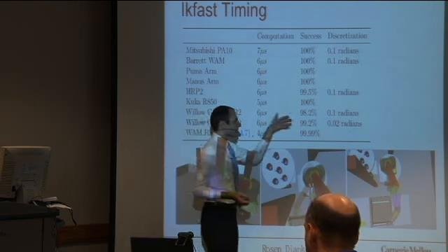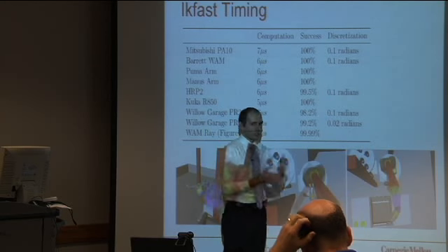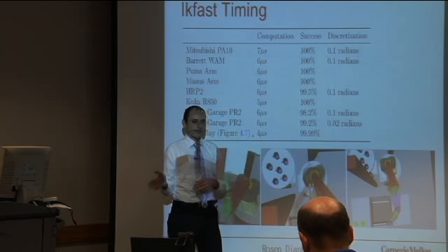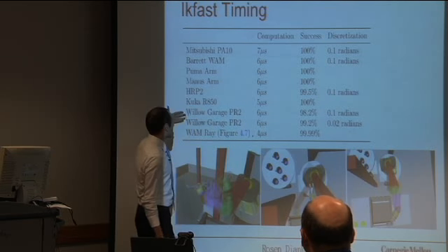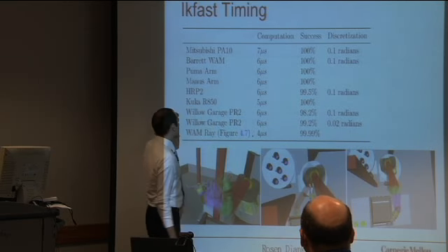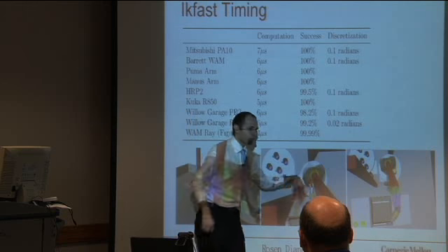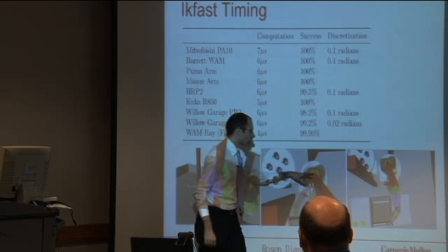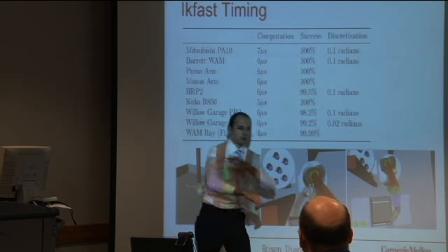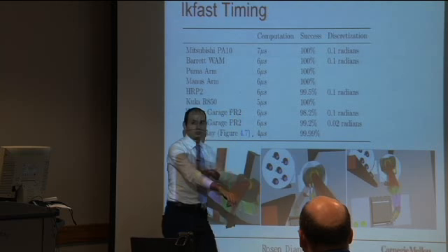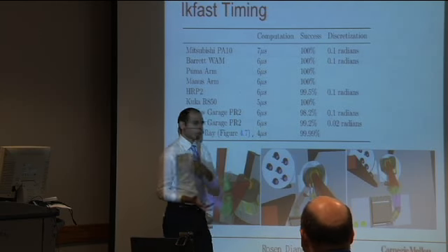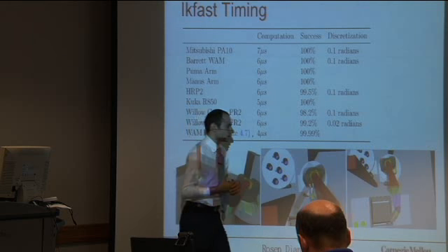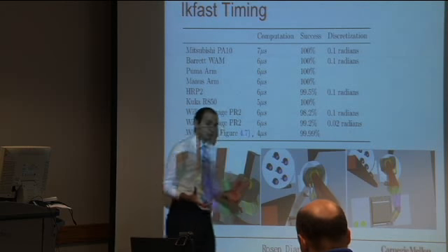And the way this happens is we actually search using a particular discretization factor of this free parameter. And what this is showing here is, for most arms, we chose the free parameter to be the one that is furthest away from the base joint, because the base joint sort of affects the robot the most. So we want the furthest away such that the whole chain is still solvable.